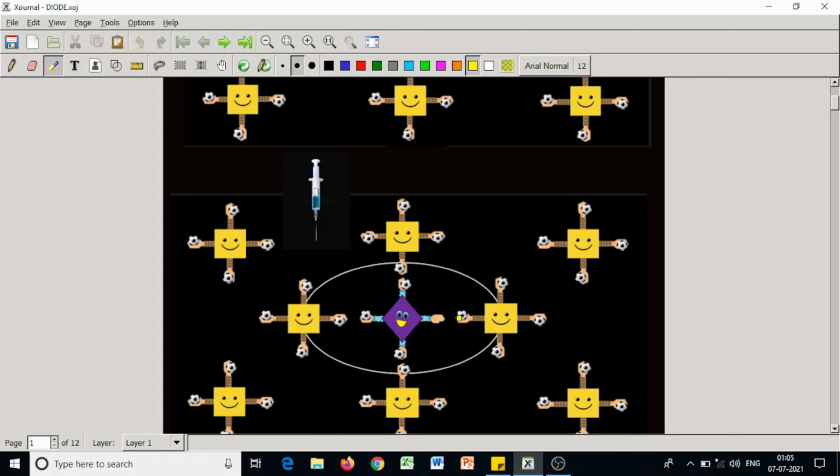So the direction of flow of electron is opposite to the direction of flow of hole. Here there is also creation of electron-hole pairs due to thermal bond cleavage at room temperature, giving rise to a few electrons as minority carriers, and holes are the majority carriers. As here positive holes are majority carriers, the name is p-type semiconductor. Here minority carriers are electrons and majority carriers are holes.